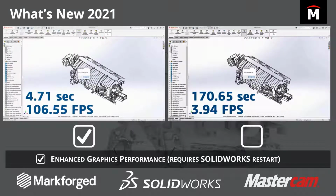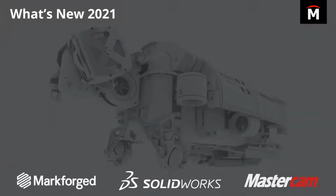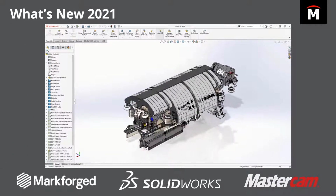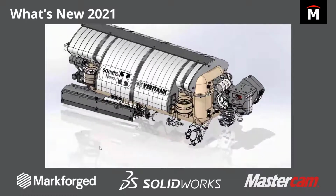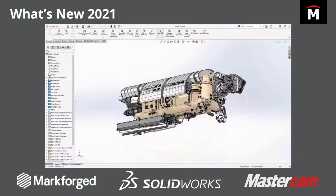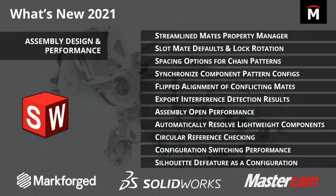Driving this is a technology called Occlusion Culling, which determines when part of the model is out of view. Only dedicated resources are used on visible components. This is super powerful if you are a large assembly designer. I was able to get a glimpse of this using a developer build of SOLIDWORKS, and here the technology is paused, so we can see what these initially out-of-view components look like in their culled state. This technology is super common in game design with large environments, as they do not render what is not currently in view. I do love gaming, but large assemblies is where my real passion is, so let's flip over into SOLIDWORKS and have a look at what we can do.